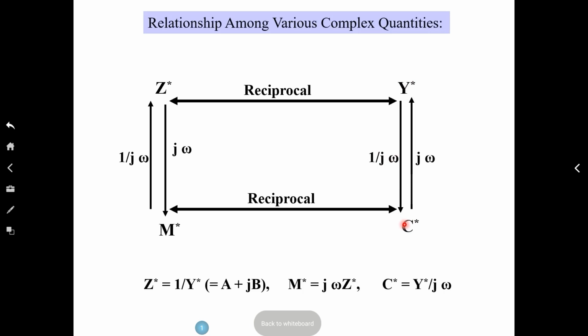You would say 90, maybe 95% of the analysis is done in impedance. But once in a while you see people do admittance plane plot, modulus plane plot, and capacitance. And you will see that multi-plane analysis sometimes gives you physics that is not revealed in one of them.